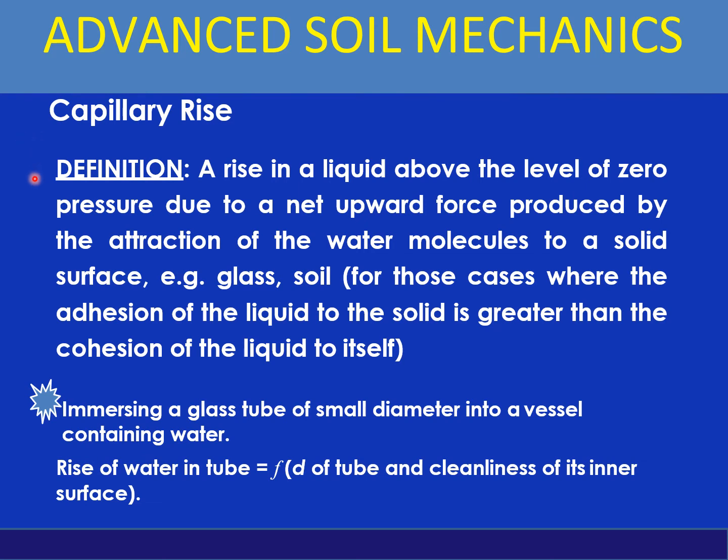Capillary rise. A rise in a liquid above the level of zero pressure due to a net upward force produced by the attraction of the water molecules to a solid surface, for example, glass, soil, for those cases where the adhesion of the liquid to the solid is greater than cohesion of the liquid to itself. So immersing a glass tube of small diameter into a vessel containing water, the rise of water in the tube is a function of the diameter of the tube and the cleanness of its inner surface.